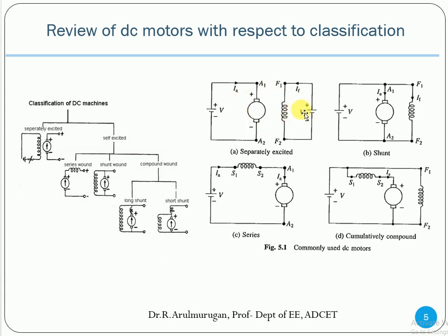Okay, so how does the rotation take place? You give the power supply to both windings. Both fluxes are created, field flux and armature flux. These two fluxes interact, and torque takes place in that rotating winding.